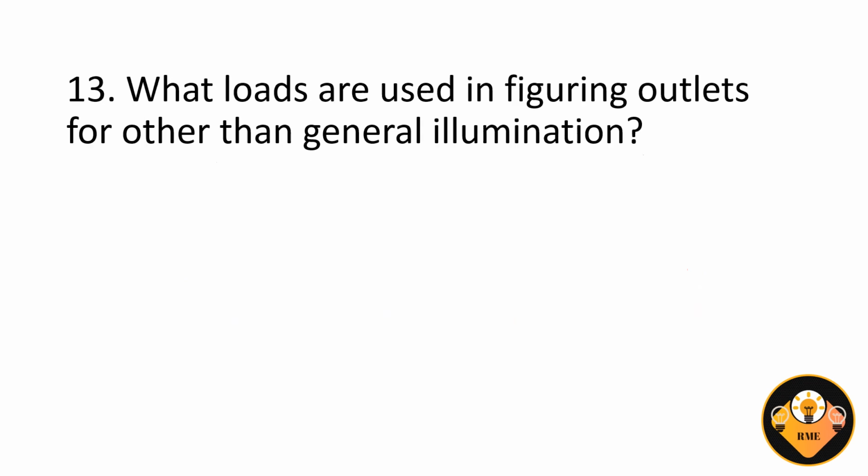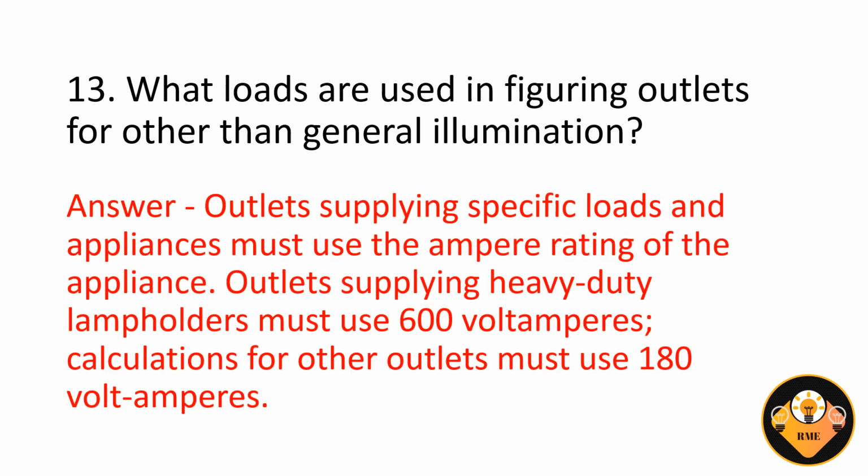Number 13. What loads are used in figuring outlets for other than general illumination? The answer is, outlets supplying specific loads and appliances must use the ampere rating of the appliance. Outlets supplying heavy-duty lampholders must use 600 volt-amperes. Calculations for other outlets must use 180 volt-amperes.